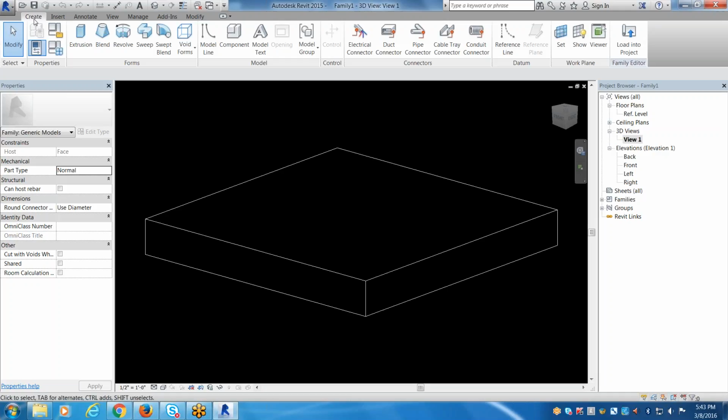That brings us to the revolve. The revolve is you create a profile of something and then revolve that around, like in pottery class. So that would be much easier. You do this side, and then revolve it around here, and that works when something's symmetrical about a center axis. You could even do it with this too, right? The revolve would work this way too.